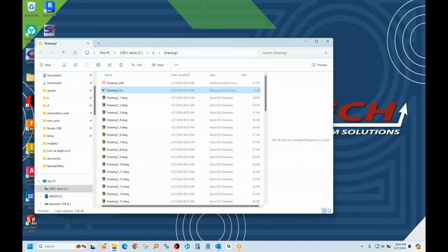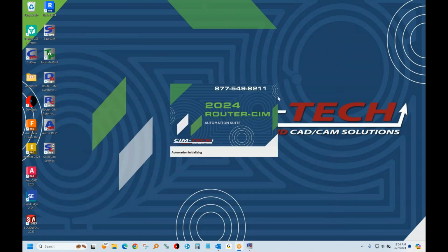At this point, you could just do the right click and cut, and it will cut and nest those parts. Now it's going to import that list so it knows the name of the part, the material, and the quantity. And it opens up each drawing, and the drawings have geometry on different layers. So that layer hole, it knows to drill that. Layer pocket cut, it knows to use a certain size tool and a feed rate and a spindle speed. Those are all machining knowledges, and those machining knowledges are associated with different layers.